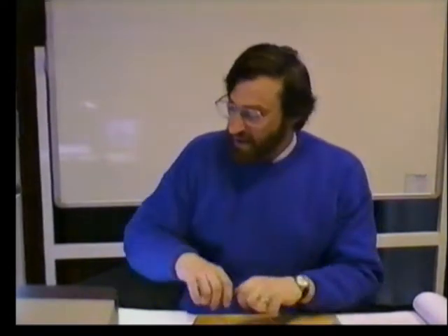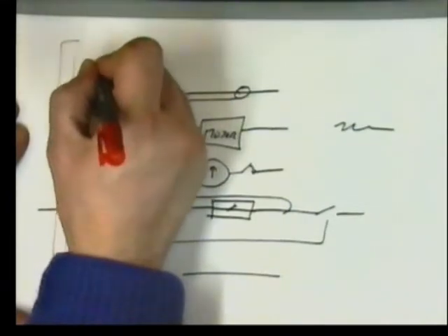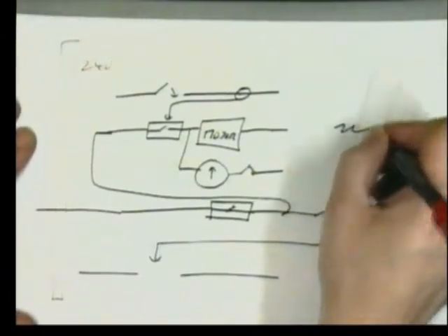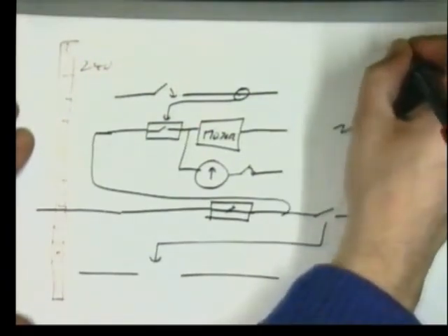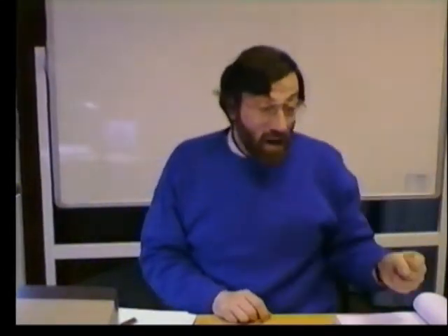And what you actually get, I haven't shown you the power supplies, but on this side of here, you would get an enormous big 24-volt power supply. On that side you had these enormous big brass rods, you could actually grip them in your fist. Go to an old factory, you'll still see these. You had Norfolks there. And what would happen is you'd start with your cabinet empty. You drop down one side a live 24-volt supply that carried tens of amps of power. So these things were dangerous. And the other side was the 0 volts.